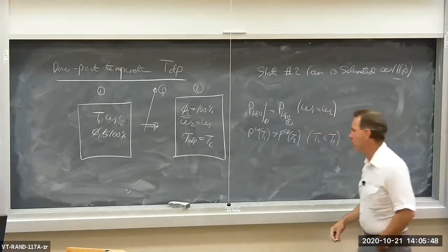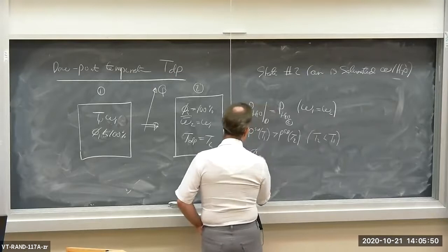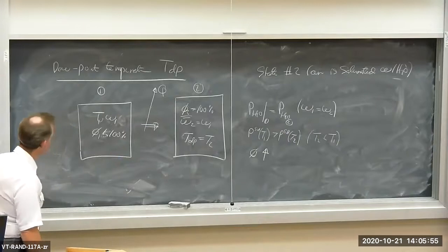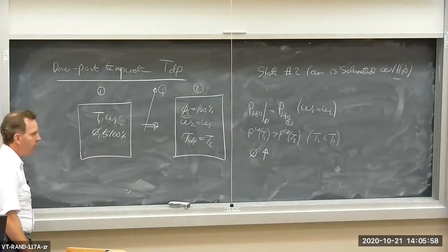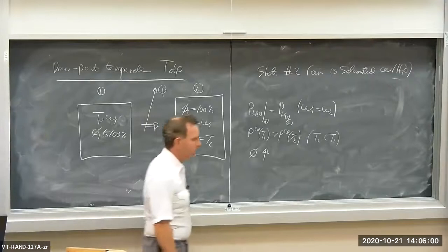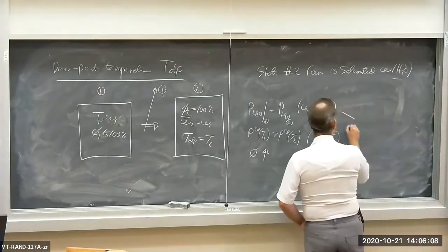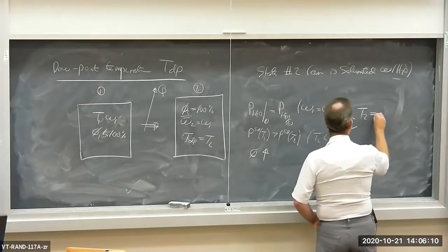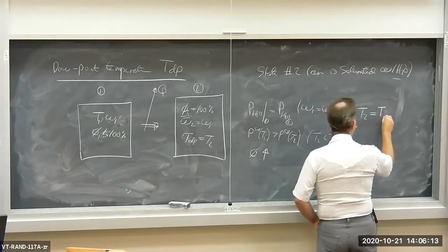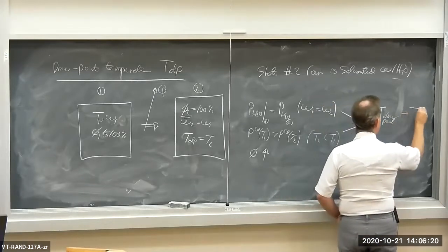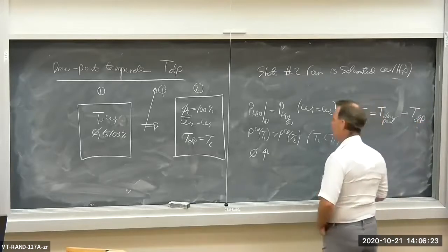And that means, of course, that relative humidity is going up. Relative humidity at state 2 is greater than state 1. So we're going to reduce the temperature until we get to a saturation point. That temperature T2 is called the dew point temperature, usually abbreviated just TDP.